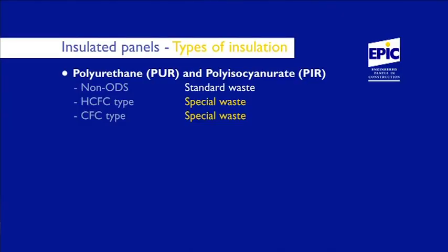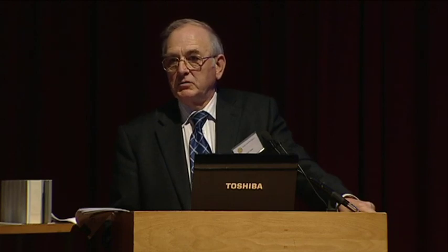Earlier panels were blown with CFC blowing agent. Because of environmental pressures, we were asked to move in the mid-80s to a non-ODS. We couldn't do it all in one swoop. We moved initially to HCFC, and as soon as possible we moved to a non-ODS. There are huge technical problems, production problems, in moving from one chemical formulation to another.